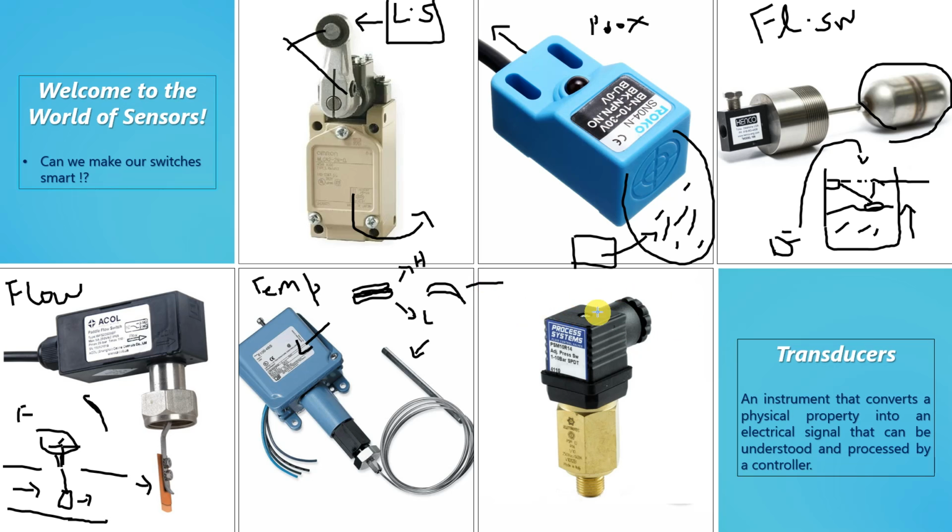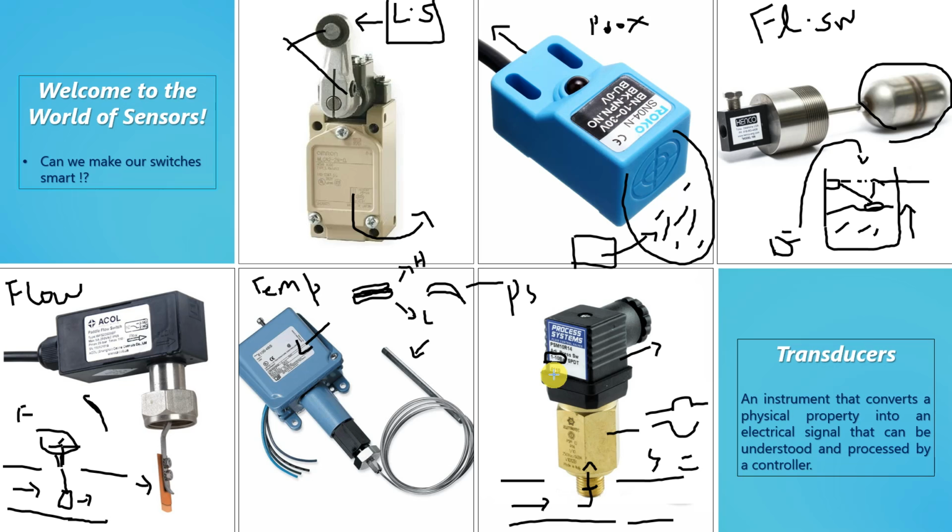The last one here is a pressure switch, right? Again, it is installed on top of a fluid pipe with the thread here. It is screwed directly into the process fluid, and the process fluid carries some sort of pressure, and this fluid will also enter this assembly right here. Now inside there can be bellows, or a spring, or even a strain gauge that can measure the pressure directly or indirectly, and the output circuit will generate at a certain pressure that is written on the top of the instrument.